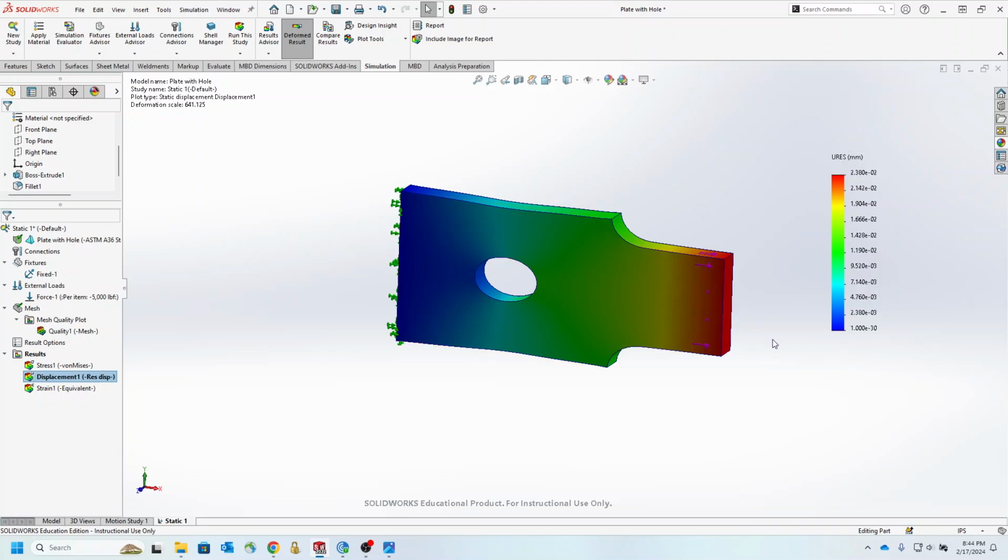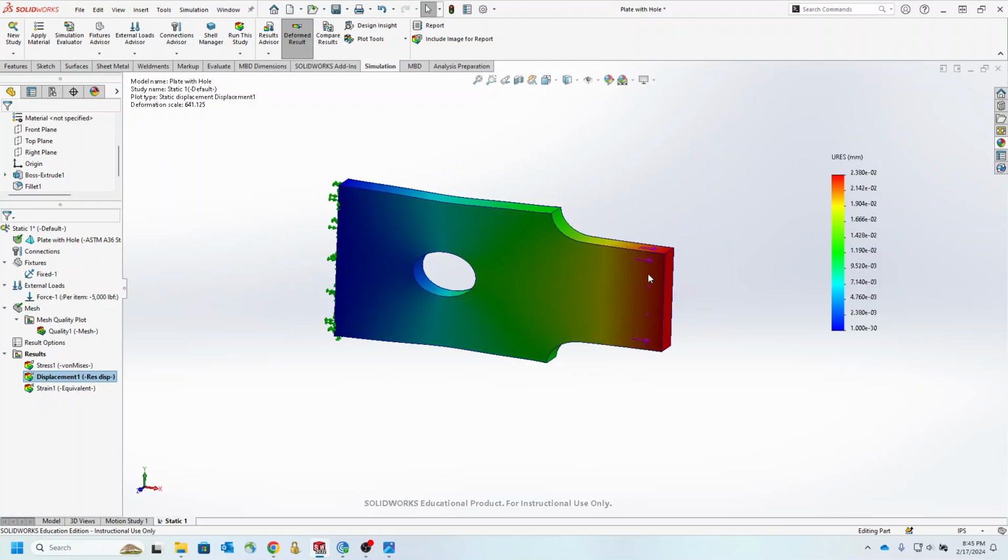Something you may notice is, number one, that this is exactly our expectation. We wanted the left part, which is close to the fixture area, to move less compared to the right part. You will see that it progresses and increases, and here you have the maximum displacement. That exactly aligns with our expectation before seeing the solution. You will see that the maximum displacement here is 0.02 and something millimeter. But the shown deformation is definitely far more than that.